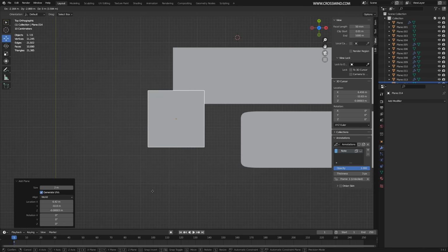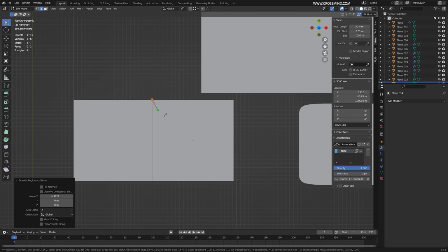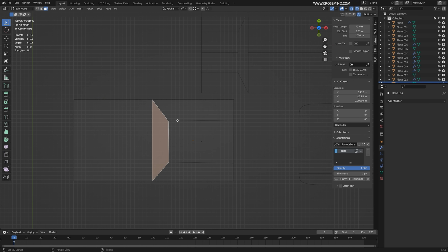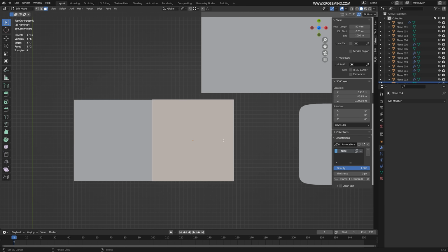Now let's try this one more time. You can simply make one cut like this. Just remember this pattern and then you can connect it through and through, and this will subdivide it. So you have quads and you have more resolution. Or you can simply inset this, delete one side and then move it here. Now you have more resolution.